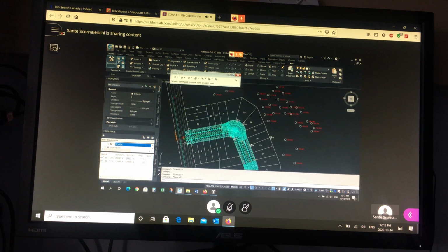Same thing with the top of the maintenance holes, right? Once you create those, once you create the pipe database, you can ask all the maintenance holes to get their elevations from the surface, right? So if the corridor and the surface for the corridor is correct, you get a lot of free stuff. So you're doing something very sophisticated in order to simplify some of the more mundane things. Okay, so it looks like a lot of work, but it saves a lot of other work. It looks like a difficult thing to do, but it makes something that's very, very boring and repetitive happen very quickly. Right? Front block corners and top maintenance elevations.